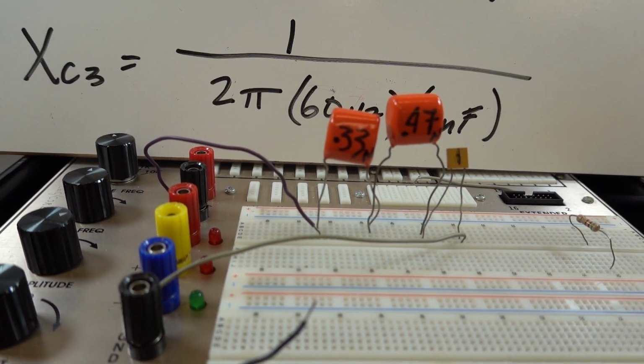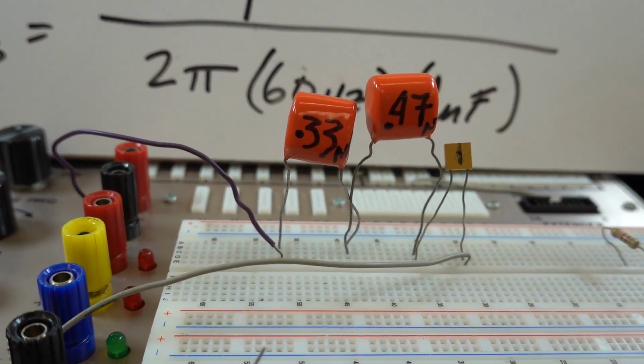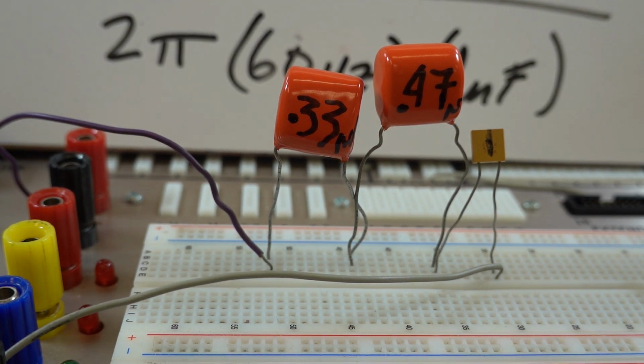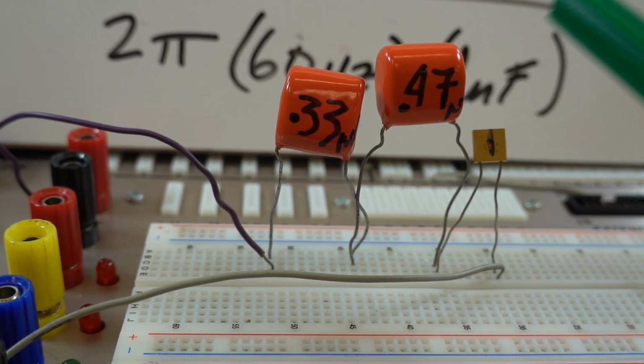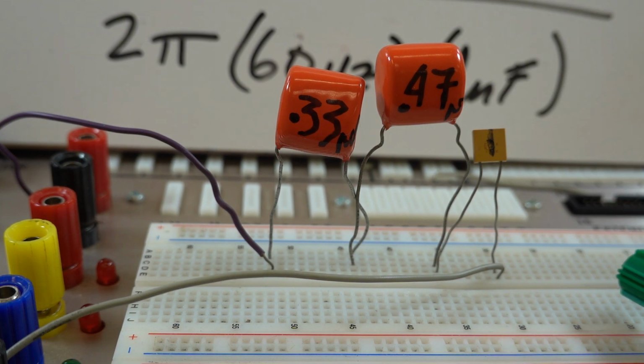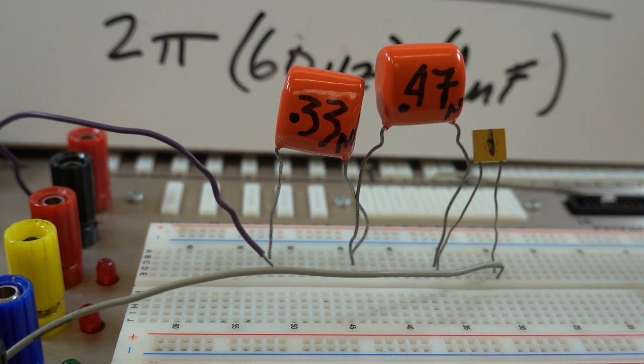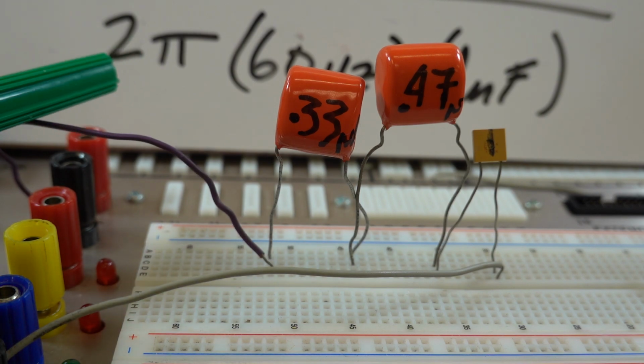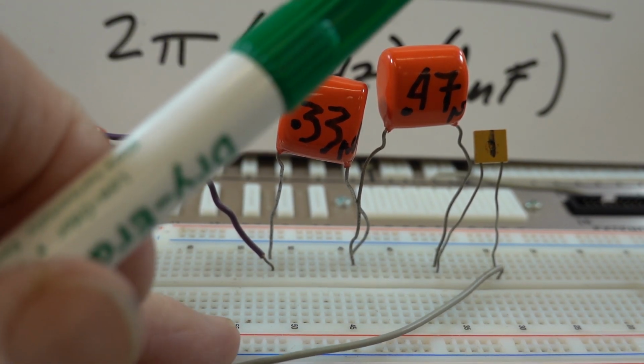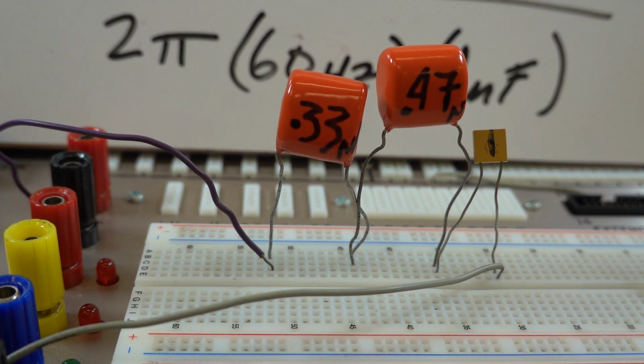And then experimentally, we're going to build this circuit, which has 3 capacitors in series, and that's what I have here. They're just in a straight row. This end is attached to one end of my function generator, or trainer, and this other end is attached to the other end of the circuit. You're going to set that up for the correct voltage, take your voltage readings, and record them on the table on page 76.